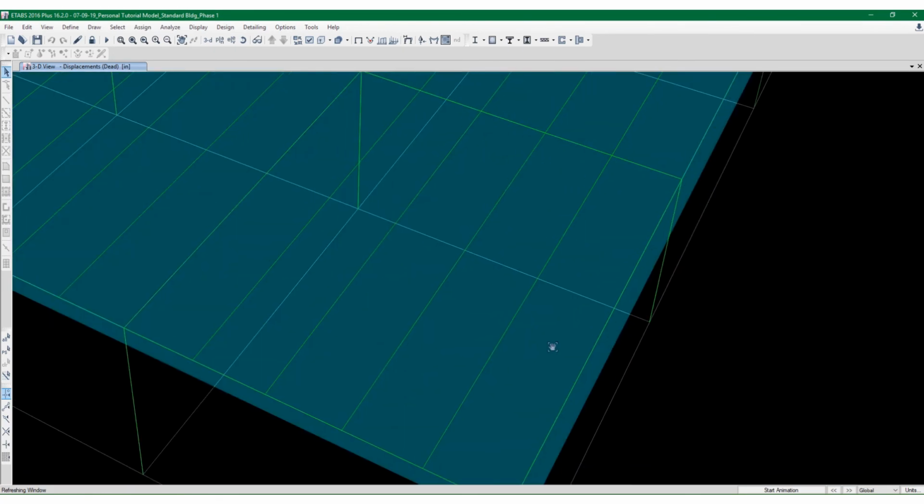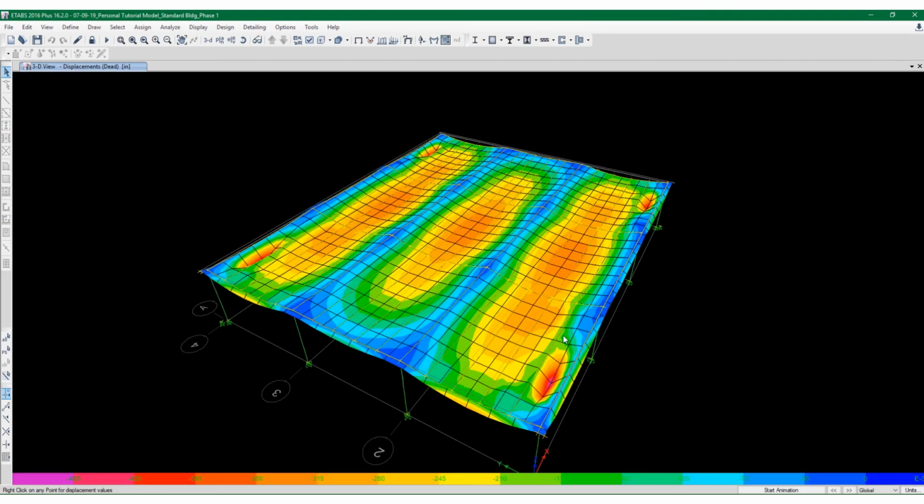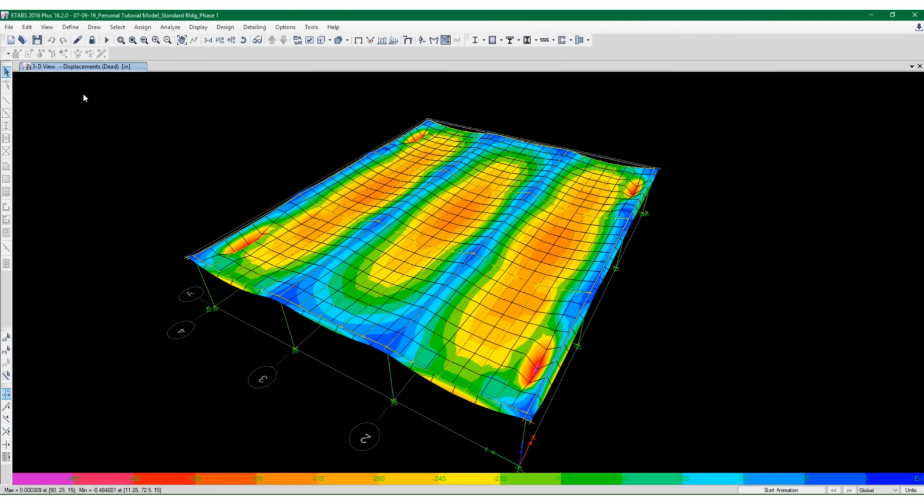All right, but in the finite element world, for what we had to model, that's what we have, because the moment of inertia was calculated, the stiffness was calculated based on a 20 gauge plate, really.